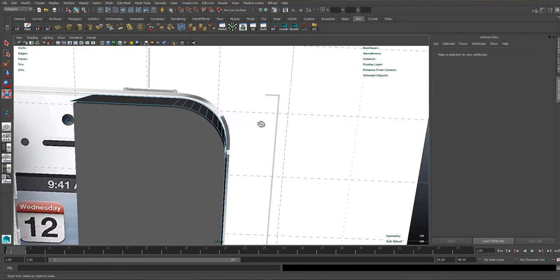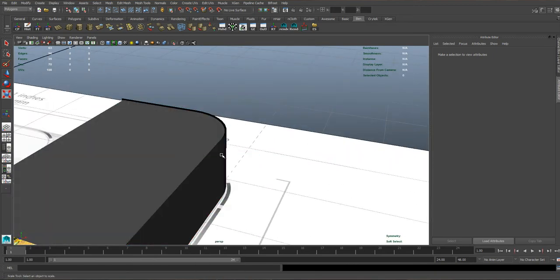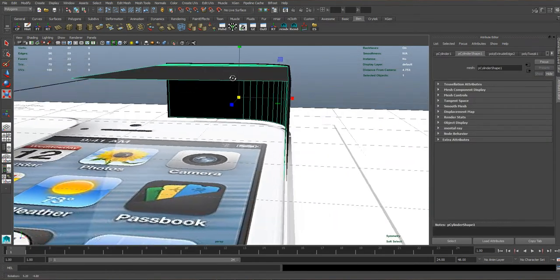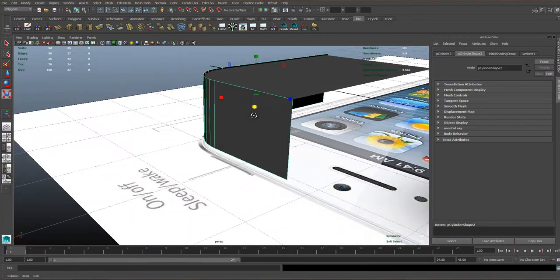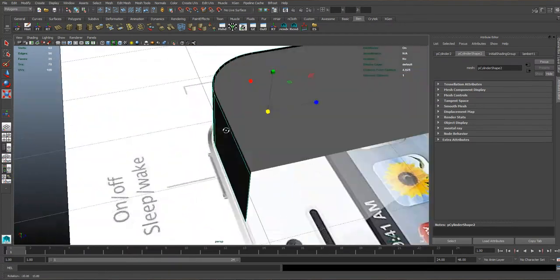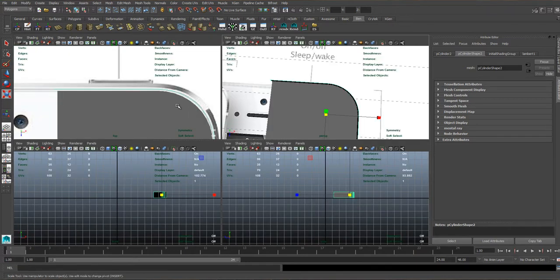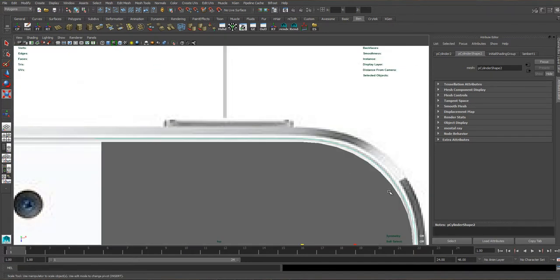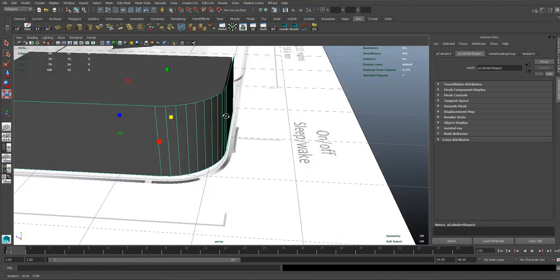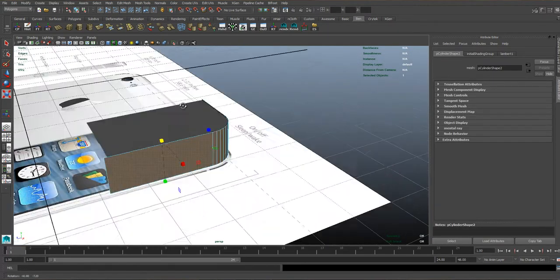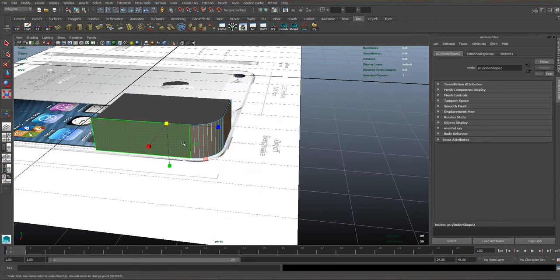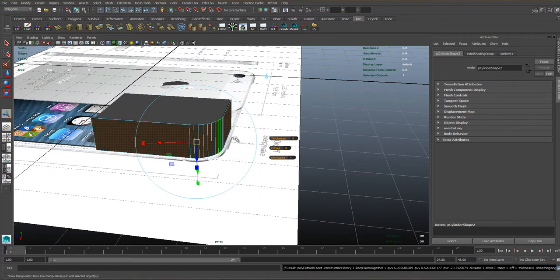And jumping back to our 3D view, you should have something that looks like this. The original geometry here, and then a resized, duplicated piece of geometry around the edge, which will allow for a small gap in between there. Next, I'm going to extrude this geometry. So I'll select the entire thing by double clicking on it, on any face, and then I'll go to extrude.